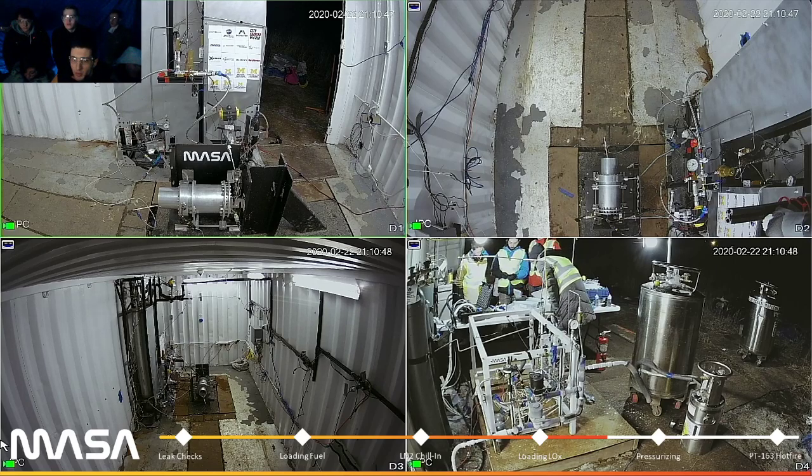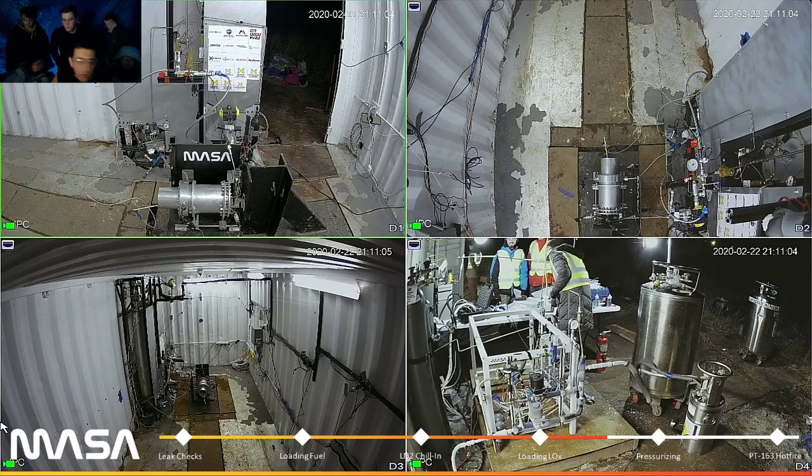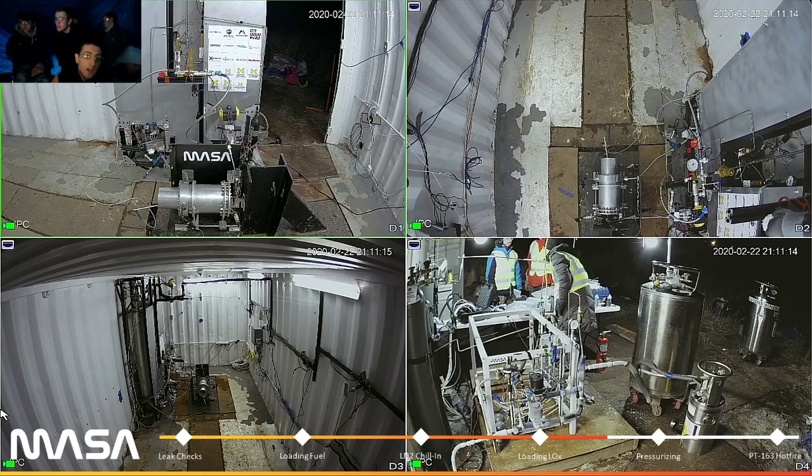We have a pretty thorough cleaning SOP that we follow to a T. It involves an industrial solvent like Simple Green, sometimes acetone, but we usually use some isopropyl to wash that off. And then a heated ultrasonic bath, drying with clean nitrogen, etc. We clean our components before we assemble them, because it would be too difficult to clean everything and ensure the level of cleanliness that we want. A big thing is being able to verify that you cleaned it. If you have an assembly, you can't really verify unless you have a tiny borescope camera.